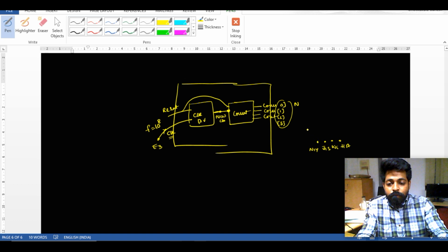So this is where I want to drive my LEDs through my output combinations. There are 4 output bits that I will be generating with the counter that I will be displaying on the 4 LEDs over here. And there will be a system clock generated from the E3. That constraint file will be as it is, and a reset I will be connecting from the switch J15. So this is your input switch.